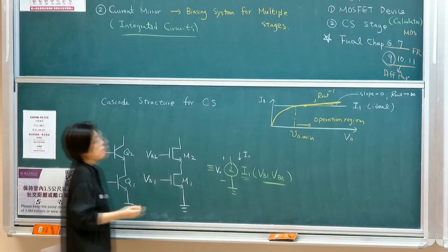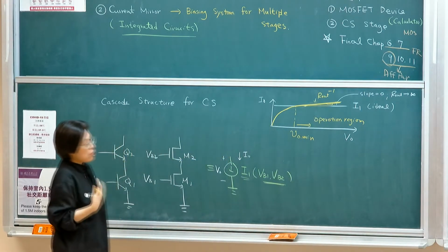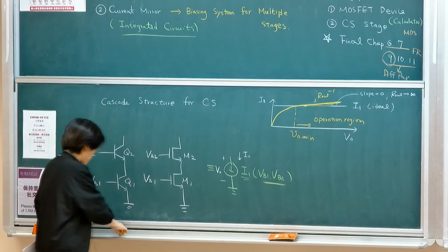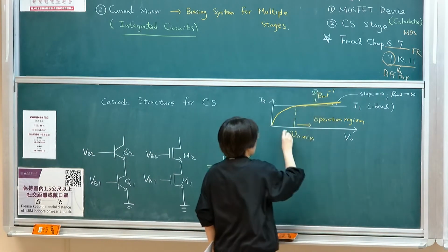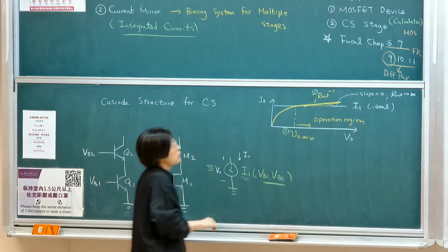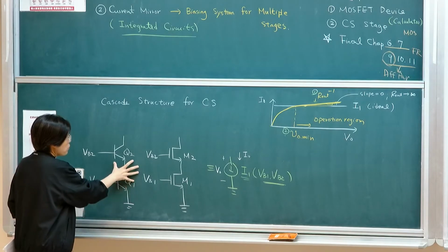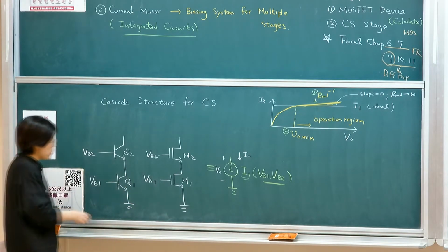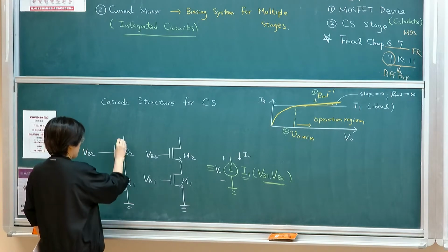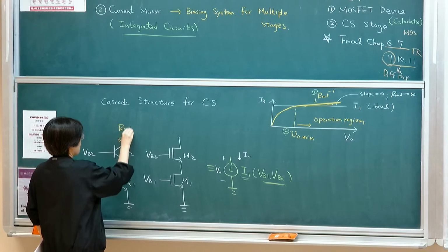Below that, it does not have a flat response, and the current level doesn't meet the target level. So it's very close. So for precision and output, there are two parameters. One is this RL, the output resistance. The other is the output VO minimum. So if I give you this circuit, you should be able to determine these two key parameters.